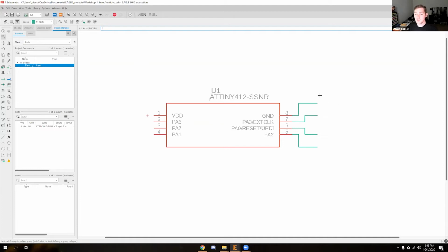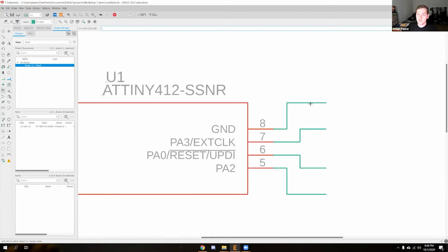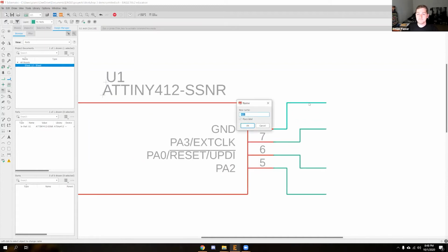Okay. So once you have this done, arranged in like a spider, we're going to do the same on the other side, but just starting on the right-hand side for now. We're going to go over to this name tool. It's the one that has R2, and there's a line, and then grayed out it says 10K underneath. So go ahead and click that. Click name. Again, that button should highlight. Nothing changes on your cursor. But then we're going to go over here, and we're just going to click this line.